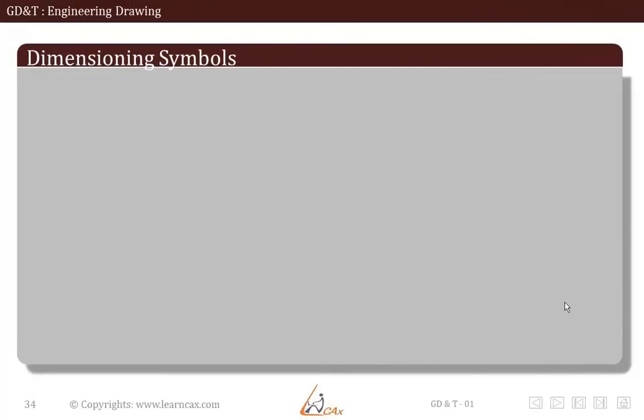Now if we revise, our basic purpose for dimensioning is to convey all related information about a part with the help of just a drawing sheet, which would not only include the part drawing but also some information regarding the part's manufacturing process, and all the rest of the details, its length, its scale, non-technical data, technical data, etc. with the help of GD&T.